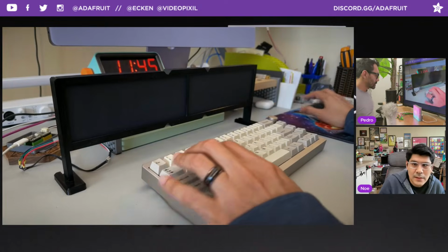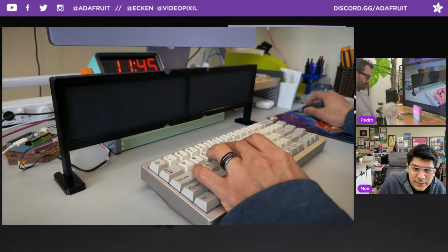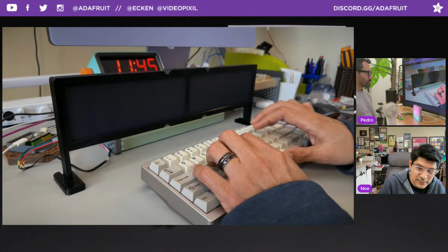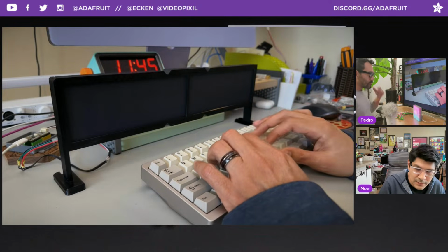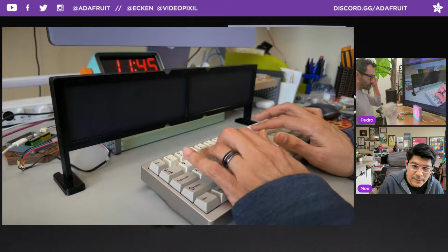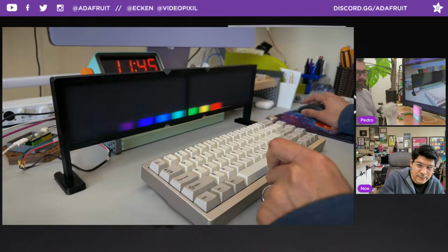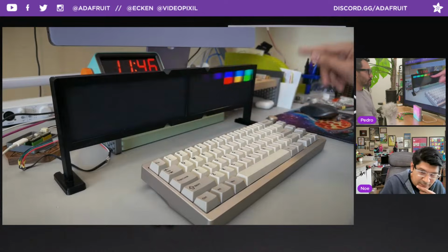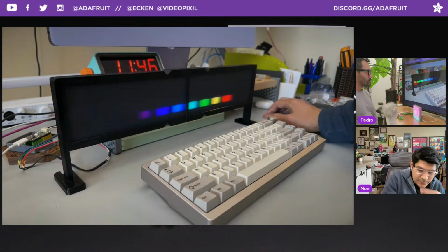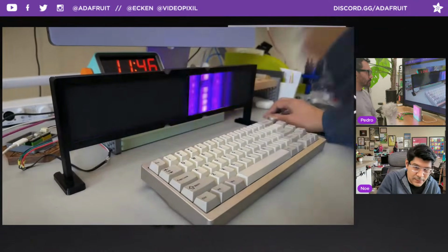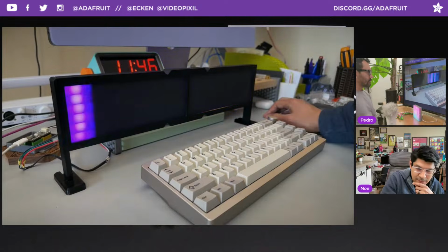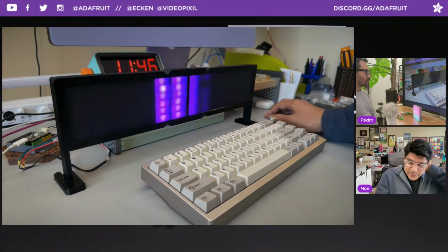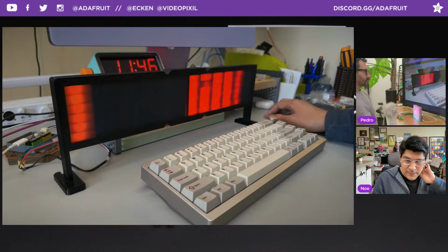And while we're here, why don't we do a quick change? I'll just change the code.py to do some LED animations, just so you can see a strand display here. It is doing the serpentine layout. That's where it daisy chains up and down. And the CircuitPython LED animation library has some special helpers for defining how you want your matrix display to be.